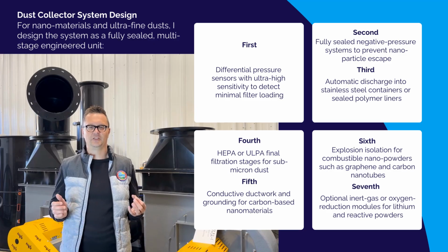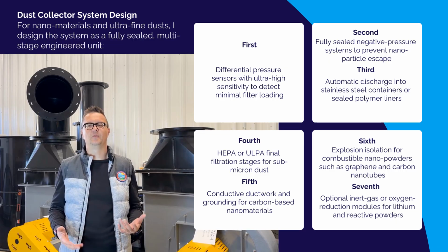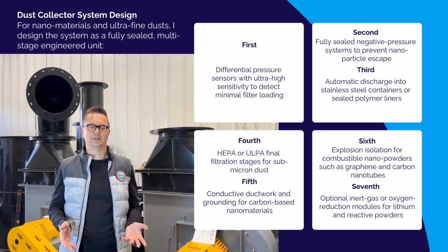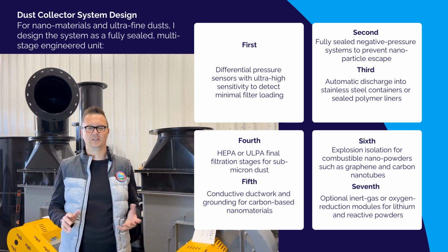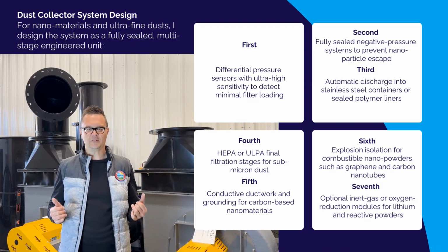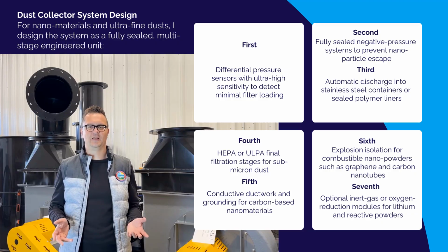Dust collector system design. For nanomaterials and ultrafine dusts, I designed the system as a fully sealed, multi-stage engineered unit. First, differential pressure sensors with ultra-high sensitivity to detect minimal filter loading. Second, fully sealed negative pressure systems to prevent nanoparticle escape. Third, automatic discharge into stainless steel containers or sealed polymer liners. Fourth, HEPA or ULPA final filtration stages for submicron dust.